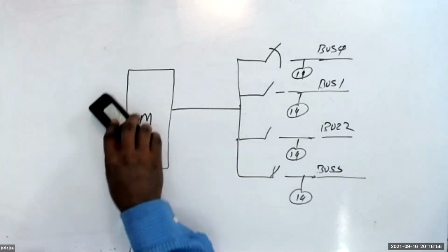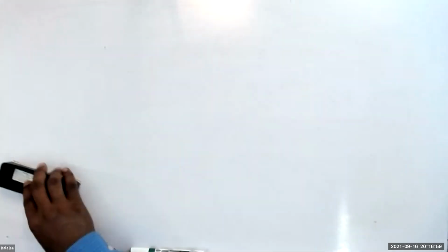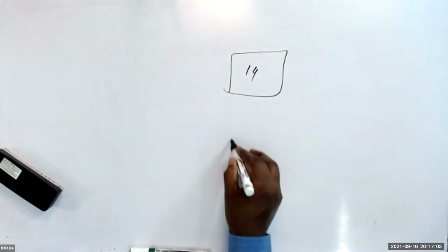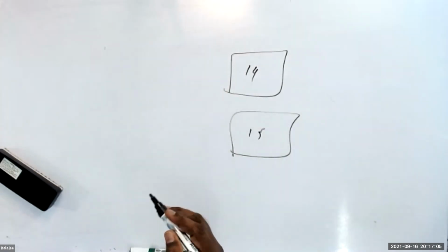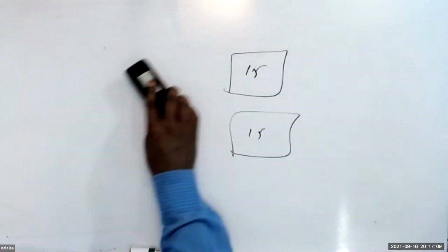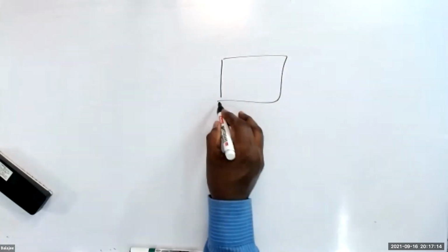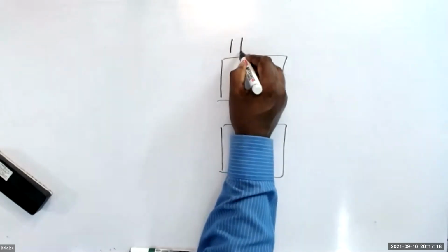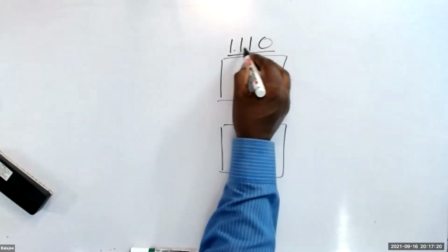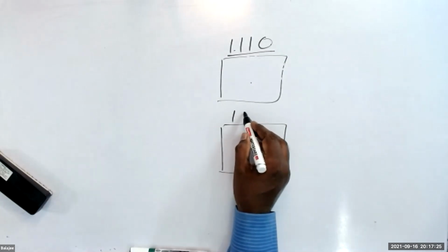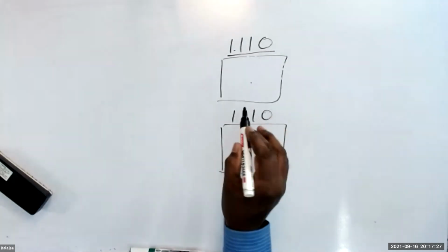But sometimes every manufacturer says that they fix the address 14, 15 like that. You buy two chips, both are having 15, you have to buy a mux. So what the manufacturer did, one interesting thing, a lot of manufacturers, if you buy a chip, they fix the first 4 bits. My first 4 bits are 1100. This guy's first 4 bits are, let's say, 1100. Both are the same chip.